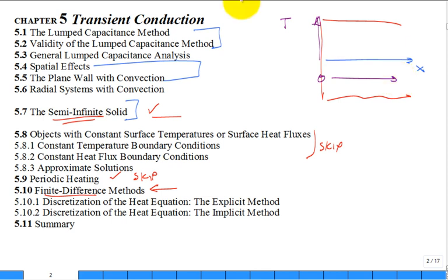And we'll think about the temperature initially as everywhere T initial inside my semi-infinite material. But then abruptly, I'll do something at that boundary. I'll move the temperature to an elevated value, maybe I move it to Ts, so it's a higher temperature, and then what's going to happen? Well, there'll be conduction into the semi-infinite solid. And so maybe a millisecond later, the temperature profile looks like this.